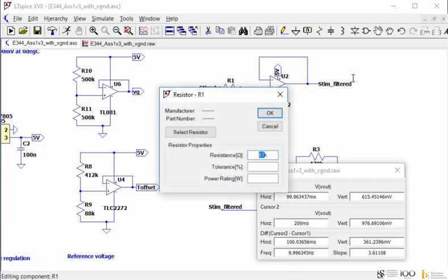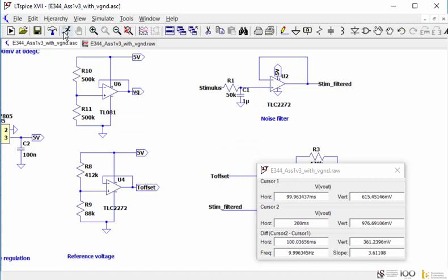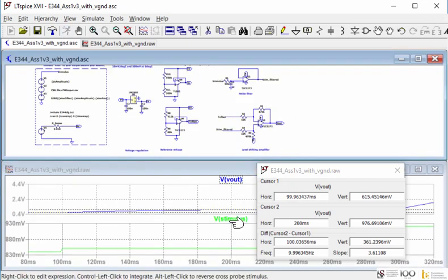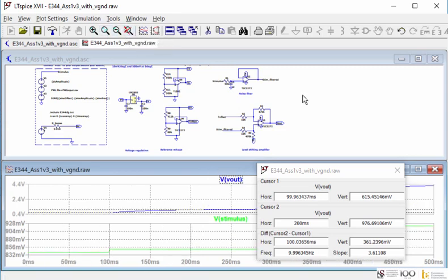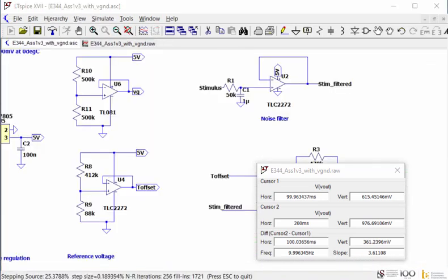So I'm fiddling around with it. You're obviously supposed to go and calculate this perfect middle point, but that is too low. So if I just rerun this, then you will see that the response time will be quicker. I'm just actually going to zoom out here so you can see what I mean. So again, the filtering was fine. I suppressed the noise, but the issue is that my response time was not good enough. So now I've changed this capacitor here, or at least this resistor here.